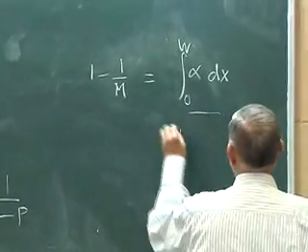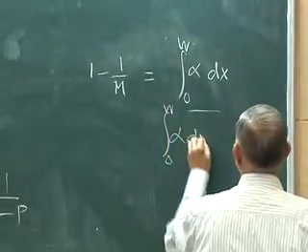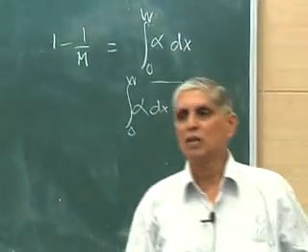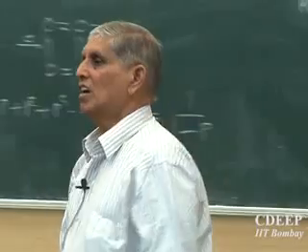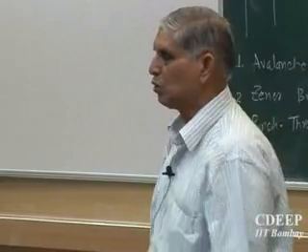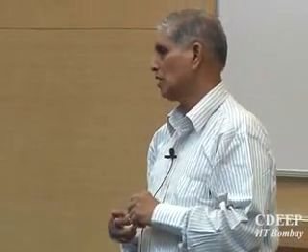So one can see from here, if this alpha integral in the depletion region tends to 1, then this value M will tend to infinite. Whenever ionization rates are functions of electric field, doping, trap densities, and many other things, real life situations may not be so trivial. But just assume in our case that this value does reach closer to 1, M tends to infinite, and therefore avalanche breakdown can occur.